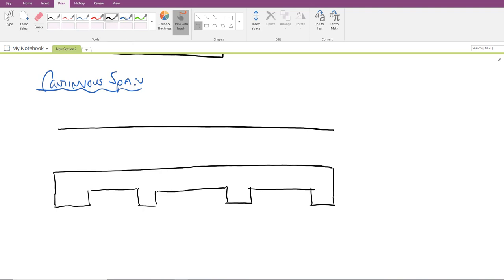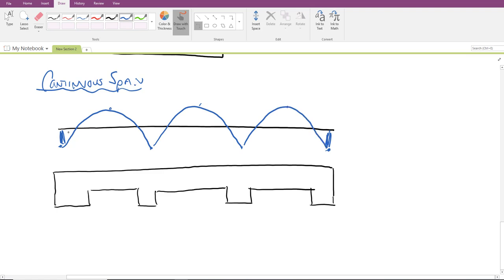If we were to go and look at our 3-span slab for the moment diagram, if you recall, what we'd end up with is everywhere we've got a support, we would have negative bending because it's a continuous beam. And at the center of all of these slabs, we'd have positive bending. And if we connect the dots, you'll recall seeing this in our common shape solutions, we end up with something that looks like this. Now note, I've got negative bending that transitions to positive bending, that transitions to negative bending, etc., all the way across.